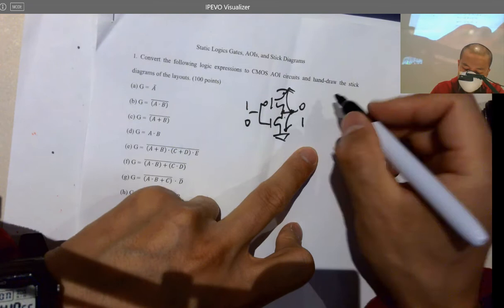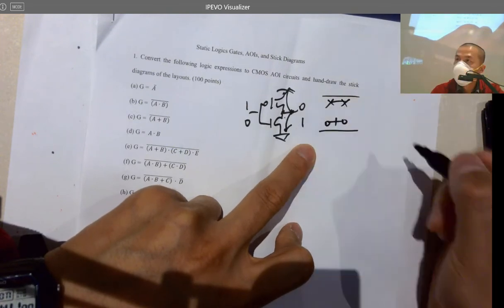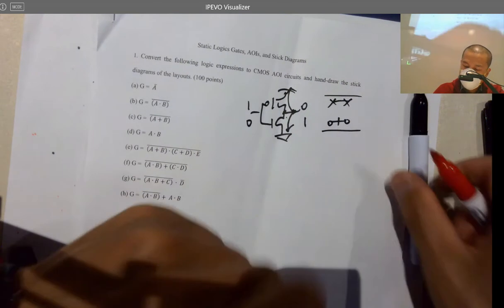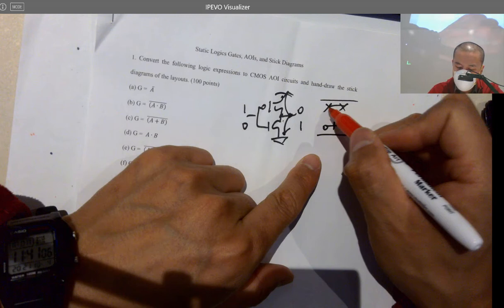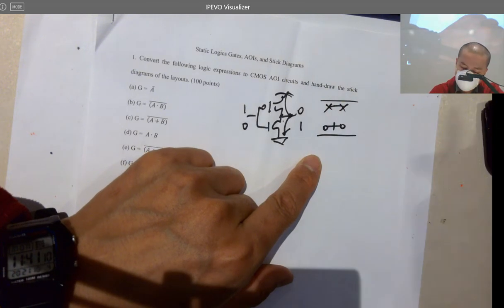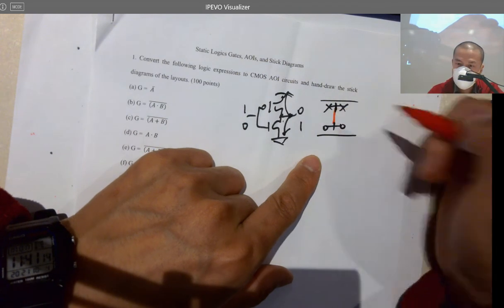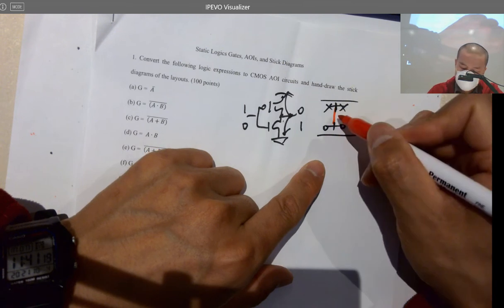And when you draw the layout, very simple and straightforward. You want to place the MOSFET in this direction instead of rotating that by 90 degrees. Okay, don't do that. The reason I want to do this is super straightforward. You can directly show the two gates together. You got one signal line. And that's the signal line.